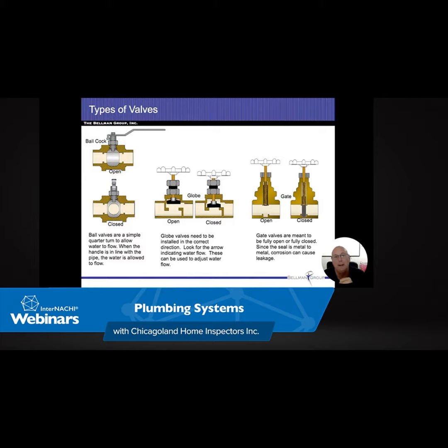And as I open that up, the water is going to go up and keep pushing that valve upwards, and then it would work just fine. What happens if somebody puts this in backwards? There will be an arrow on the outside of these things, which does show the water flow, which way it's supposed to go in there. So we can check for that.